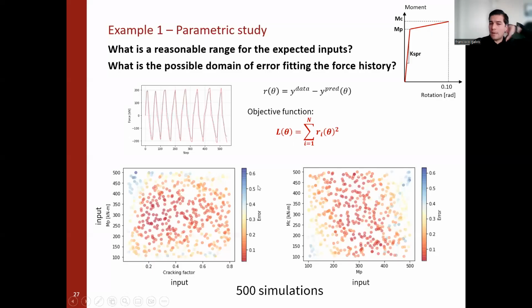So going back to the slides, the result of the parametric study is just an evaluation of the design space. The error is the sum of the square error if we haven't defined anything different. And this is a really good way to understand how far we are and what the range of the error is. We're seeing that for this problem, the range of the error is a value less than 1, and in the good regions it's really lower than 0.1.